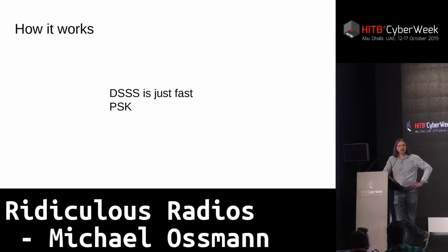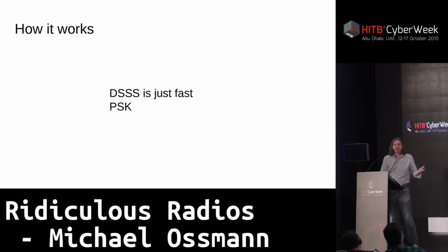And if you really look under the hood of what direct sequence spread spectrum is, all it is is really fast phase shift keying. It's just really fast with a bunch of redundant bits in it. That's all DSSS is. And so we said, hey, if we can transmit binary phase shift keying at 11 million bits per second, we should be able to actually emulate the 1 megabit per second management frames that all Wi-Fi networks use. And that's what we did.